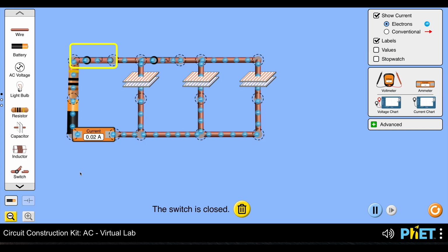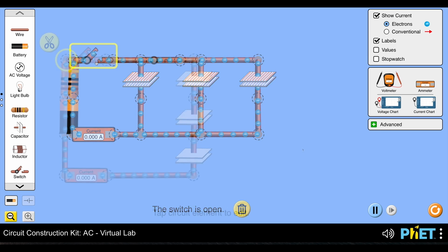If you look at those capacitors, now that we've cut the current basically down to zero, you'll notice that the overall charge on each capacitor is identical to what we saw in that single capacitor case. So if you look at the density of the positive and negative charges on those top and bottom plates, you'll see that it's exactly the same for each of these 3 capacitors as it was for the individual capacitor in that single capacitor circuit. We've basically reached zero current at this point, so I'll stop this, rebuild the circuit so we can look at a case of capacitors in series.